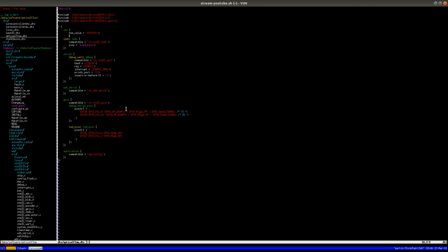And then I want to specify the HCLK div, which is the divider for the main system clock. Or actually no, HCLK div is for the AHB bus, to which pretty much all the peripherals are connected. I think I have to actually check the clock tree to be able to tell you for sure.